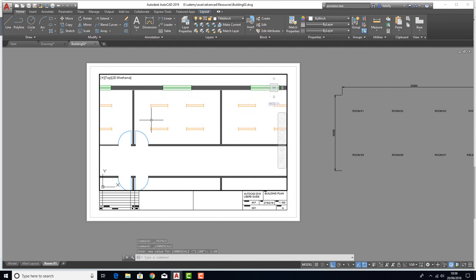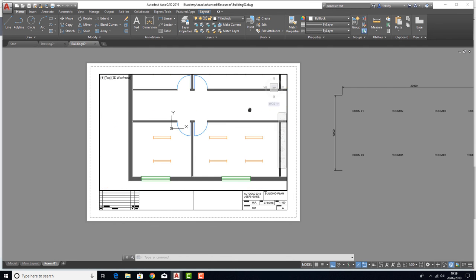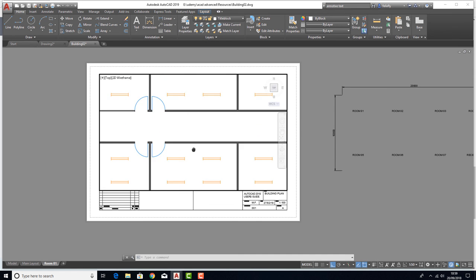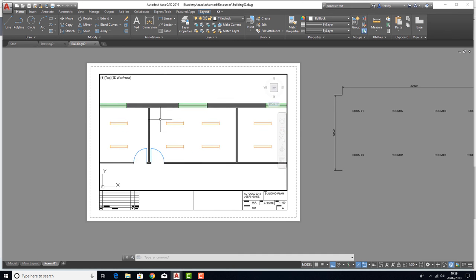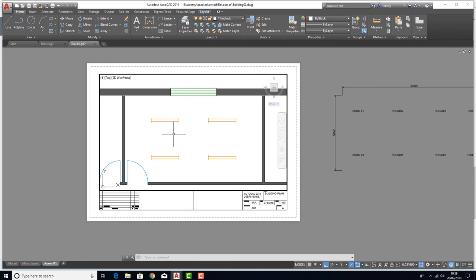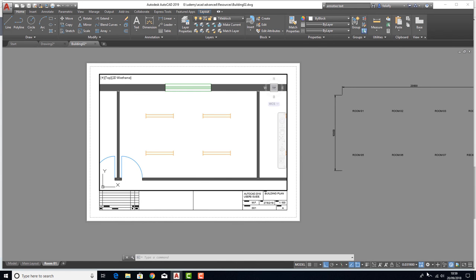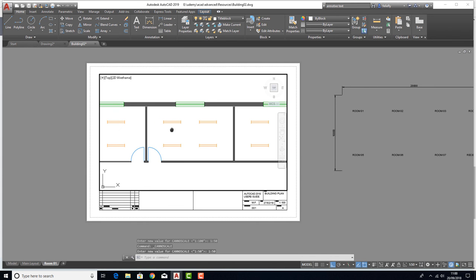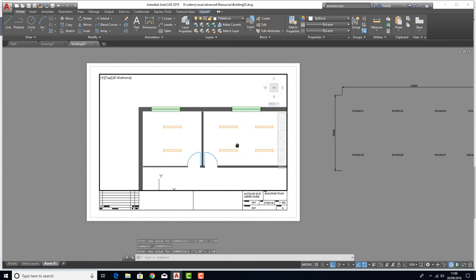And we want all our rooms to be the same scale. We don't want different scales for each drawing, so use the biggest one to set your scale. Yeah, that fits in nicely. We have room around the outside of it for some text. We wouldn't want it something like that, it's too big. Okay, so give yourself plenty of room for text. You don't want a drawing looking too cluttered. That looks okay to me, so we'll use that.